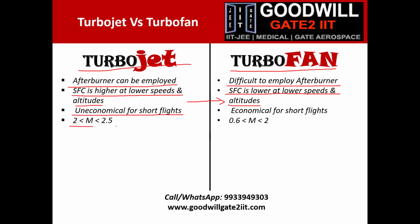You can see the design Mach numbers at which a turbojet engine should fly is between Mach 2 and 2.5. Whereas turbofan engines can fly at lower speeds and at high speeds. The reason being, you can control your fan, and depending upon that fan, whether it is low bypass or high bypass, you can use it for various applications.